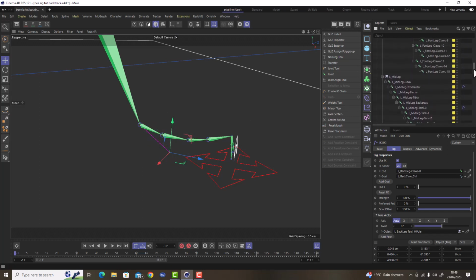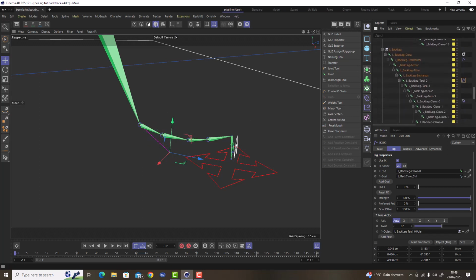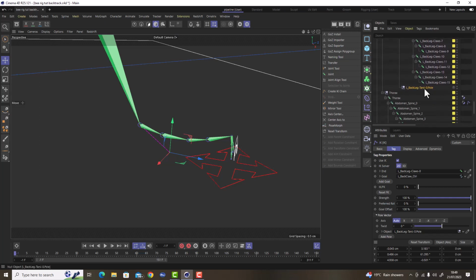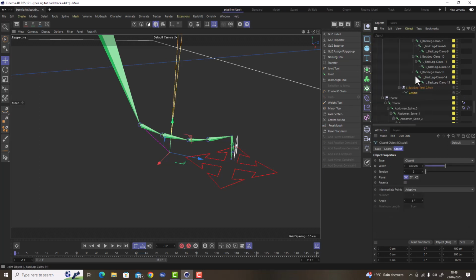That's really the main thing. So as an example there, if I leave that there, it shouldn't be too much of a problem for now. Maybe later on we can try different things, but I'm going to do the same thing. I'm just going to select this, hold down the shift key, go to our splines. I'm going to add a similar kind of shape, but this one's going to be smaller, and we're going to hold down the Alt key and do it in increments.